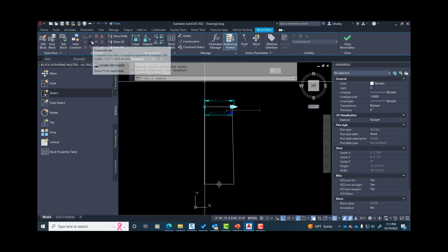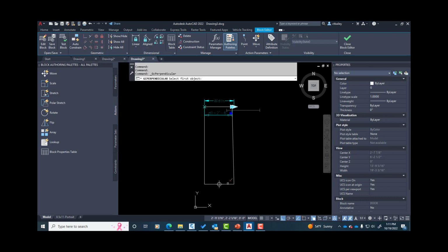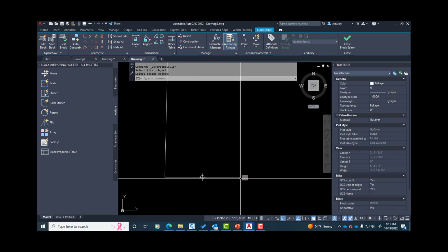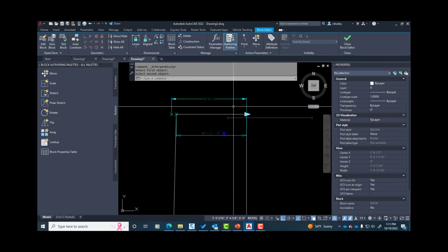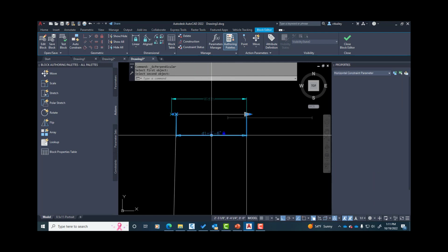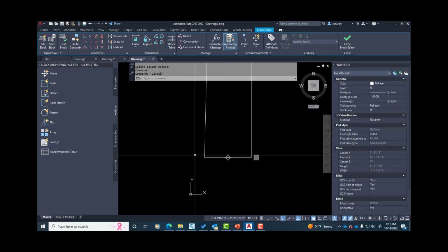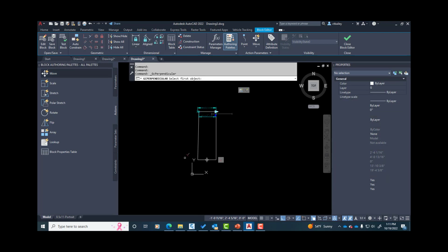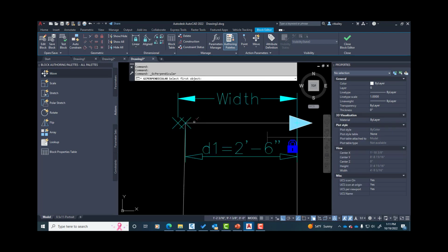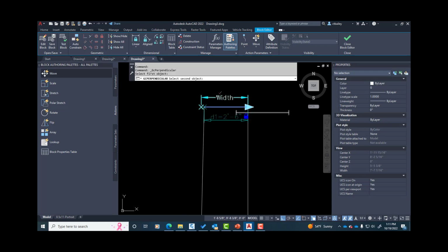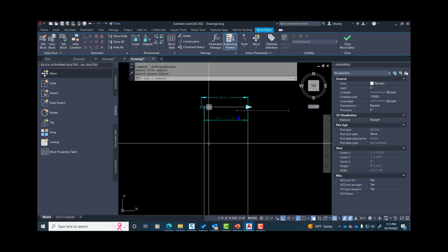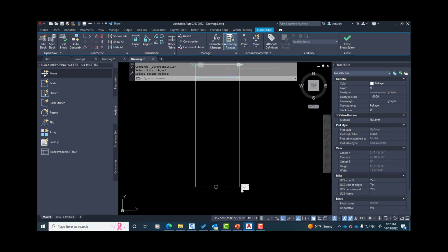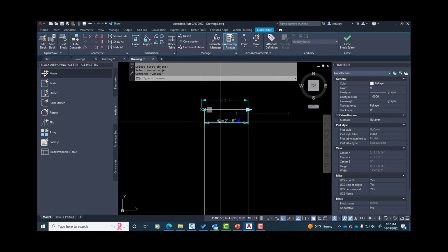And there's your perpendicular. This is the controlling line segment for the part that we want to control. Alright, so that is now perpendicular. That is now still 30 inches. But we should also perpendicularize the door as well. And so let's go ahead and do that. Let's say the top of the door controls the perpendicularity of that side of the door. There we go. We're back to a perfect door. And let's go ahead and delete that.